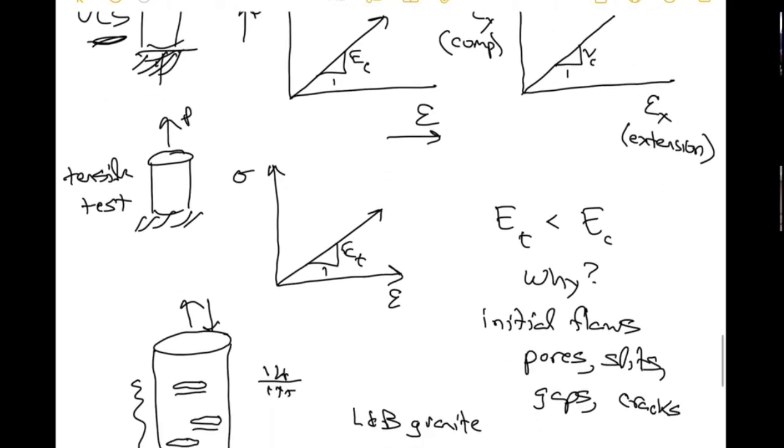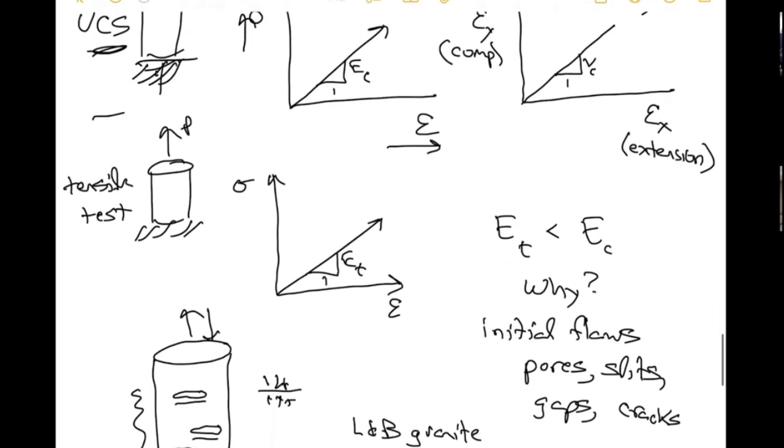Oh, and here's another thing. Remember I said this test, direct tensile test, this is a direct tensile test, is often not done in rock mechanics. It's a pain. You'd have to take a plate of steel and use an epoxy and glue it to the top. And you'd have to glue the bottom to some big steel plate, and then you could do a test like this.